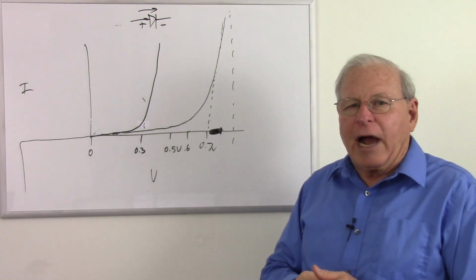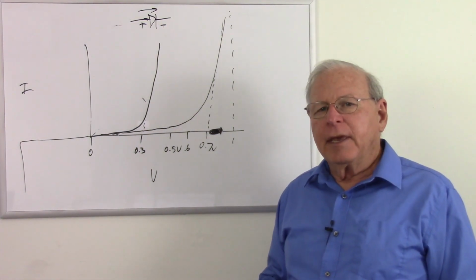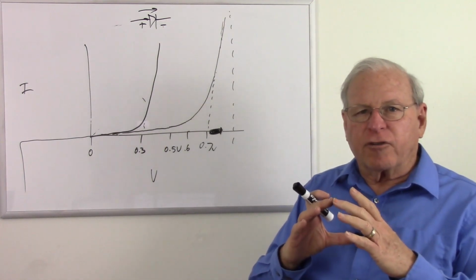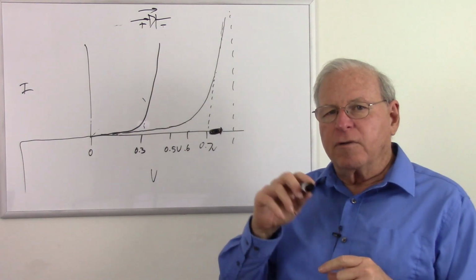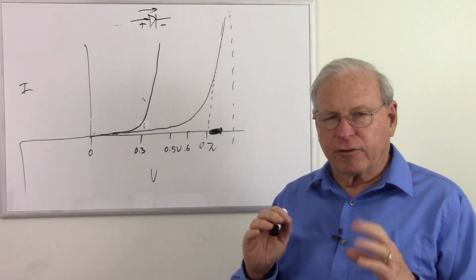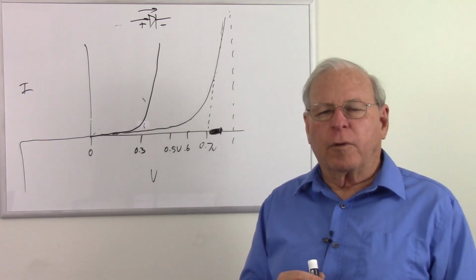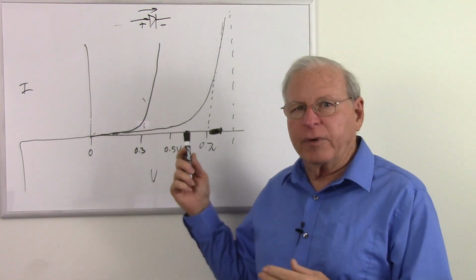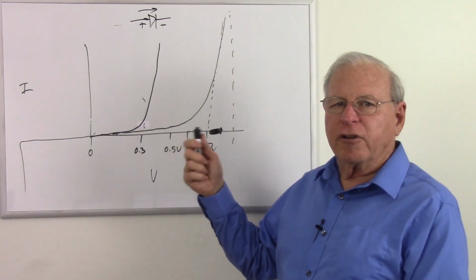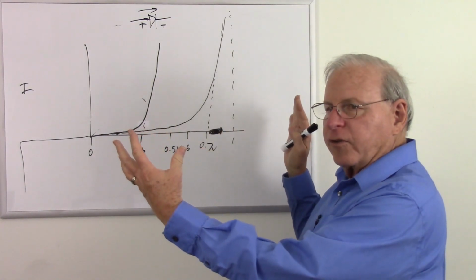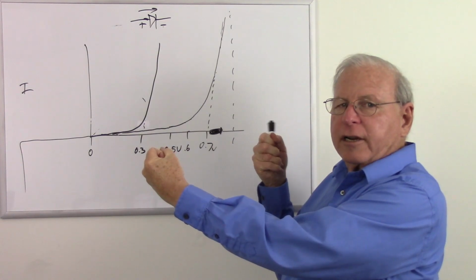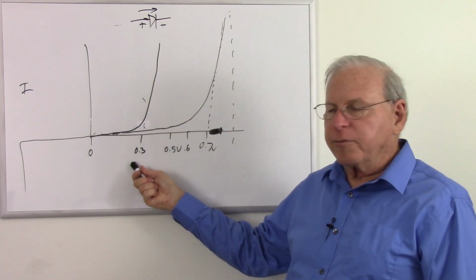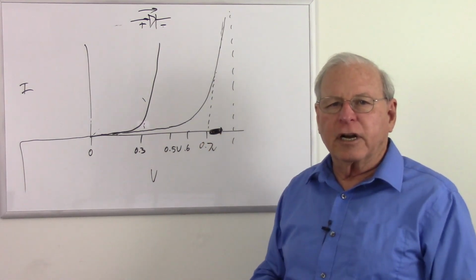So what we have are our semiconducting materials, which are carbon, silicon, and germanium. We put them together into a block of material. We get what's called a covalent bond, where there's 4 electrons around each atom, but in the covalent bond they have 8. Remember that atoms like to have 8 electrons around there, so they're stable. And so when these semiconductors form this covalent bond in a block, they are non-conductive, but we put impurities in there which cause the characteristics that we talked about before, creating the depletion region when charge carriers jump from one side of the junction to another. We reverse bias it, it pulls those charge carriers further apart so it doesn't conduct. We forward bias it, we put them closer together. And if we get it forward biased to a particular voltage, about 0.3 volts for germanium, about 0.7 volts for silicon, it will start to conduct like gangbusters.